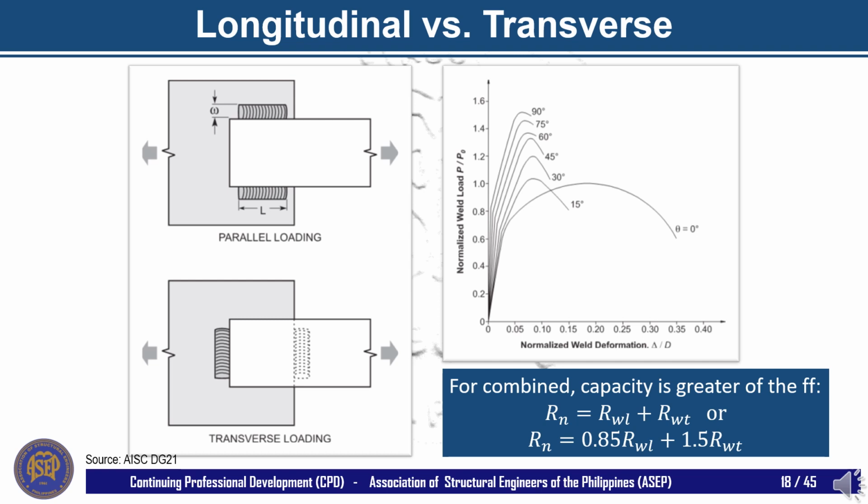Traditionally, fillet welds are designed to resist the load at the weld's throat, regardless of the direction of loading. Experience and experimentation, however, have shown that a fillet weld loaded perpendicular to its axis is approximately 50% stronger than the same weld loaded parallel to its axis. When the direction of loading is considered in design, smaller fillet welds may be possible, resulting in better design economy.